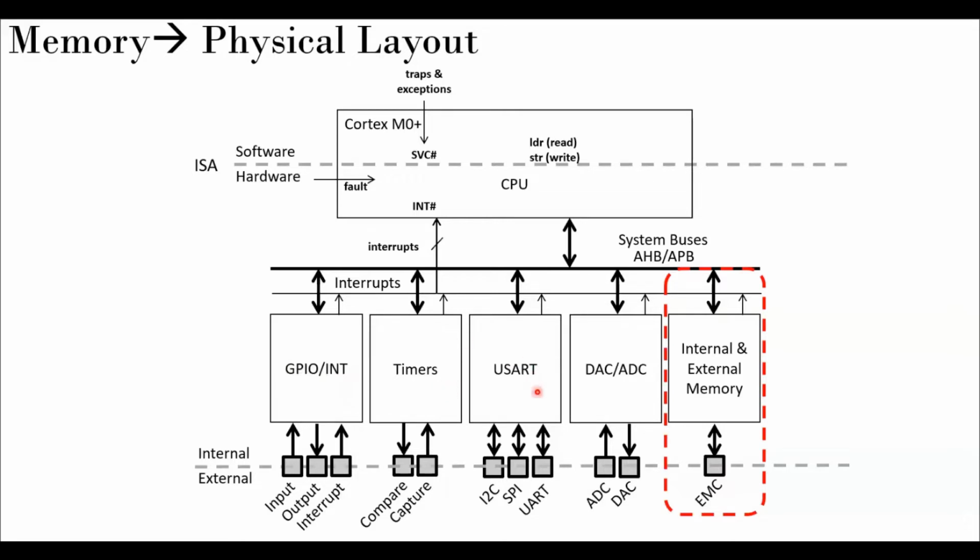And then we discussed serial communication first. Serial communication is important because parallel is sort of impossible in modern day embedded systems because of size and power constraints. So typically we communicate with peripheral devices using serial communication protocols. We discussed in detail individual sessions on UART, which is an asynchronous transmission protocol, Universal Asynchronous Receiver Transmitter. Of course, it is a single line transmission or reception scheme, and some people call it a one-on-one or simplex scheme. And then we discussed the SPI protocol, which is a 4-wire or 4+ wire system.